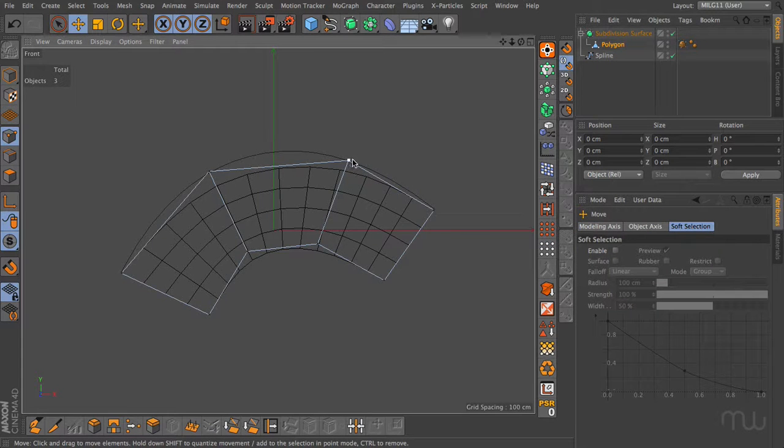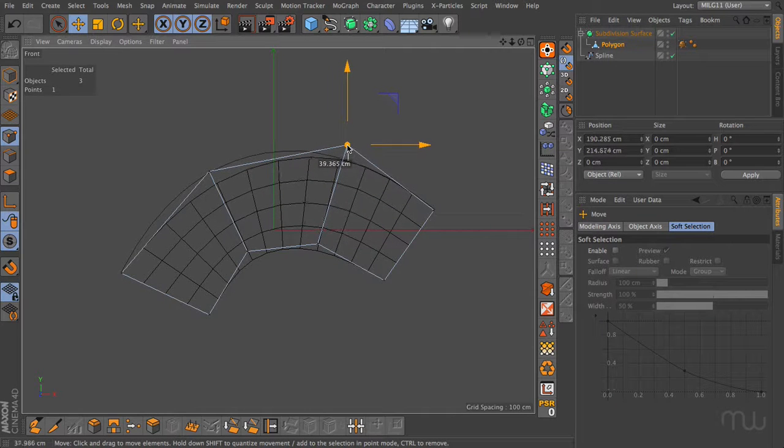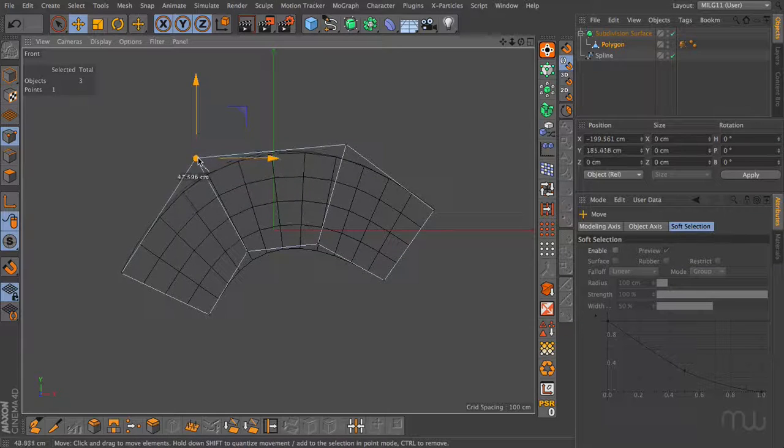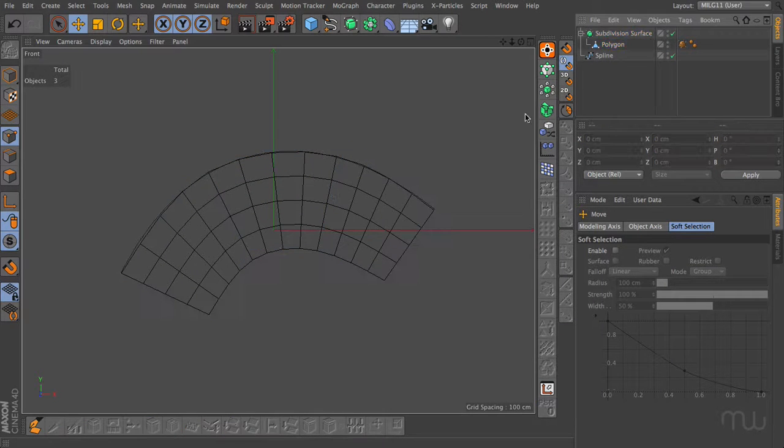So I'm pretty much going to want to place these 2 points here in the same kind of ballpark as my B-spline curves, overshooting the curve I'm trying to make. And you can see that once I do this, our curvature matches up pretty good.